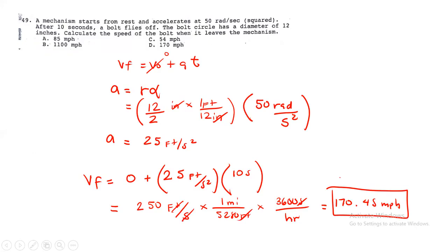So, next. So, 50, a 6 inches long, 1/2 inch diameter, 304 stainless steel rod is being reduced in diameter to 0.48 inches by turning on a lathe. The spindle rotates at N 400 RPM and the tool is traveling at an axial speed of 8 inches per minute. So, hinanap dito, calculate the feed in inches per revolution.